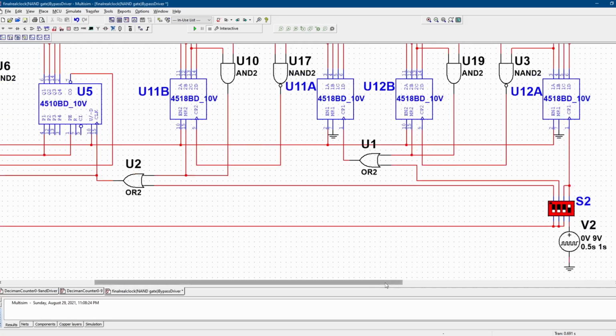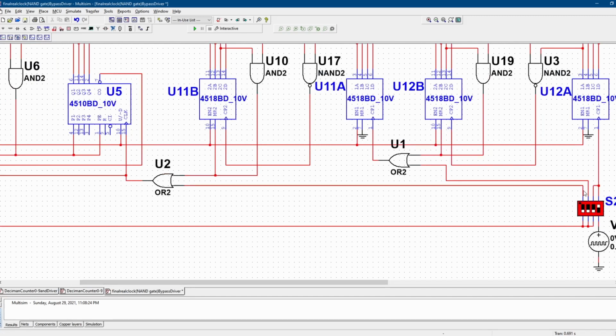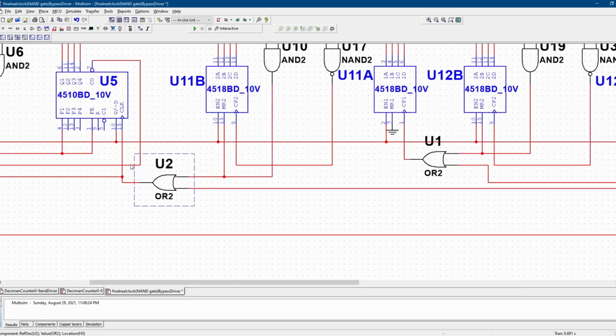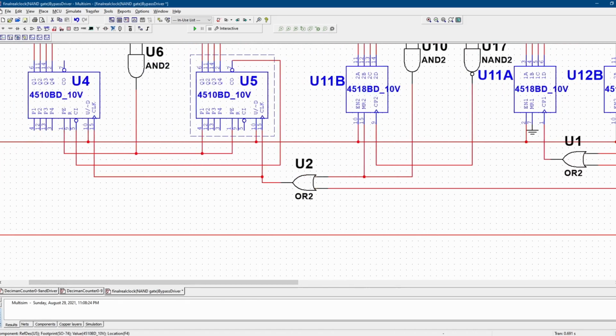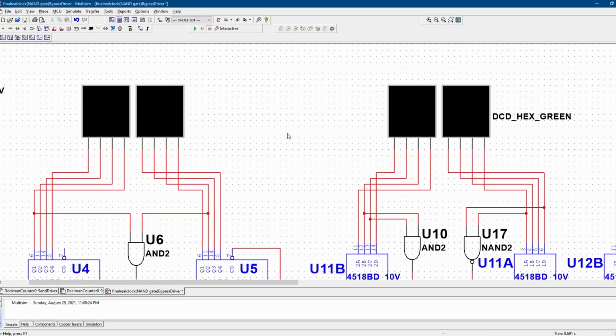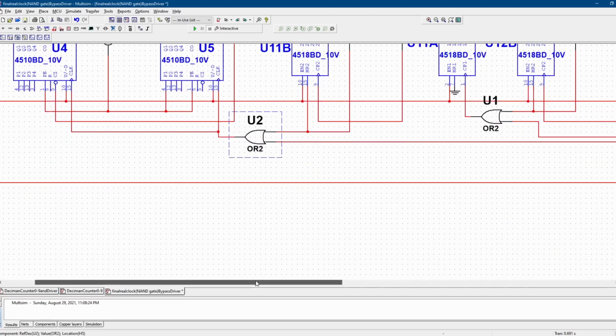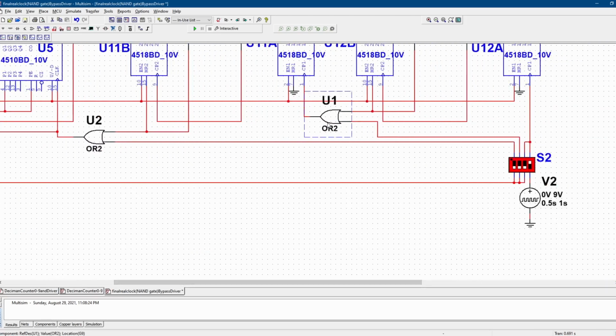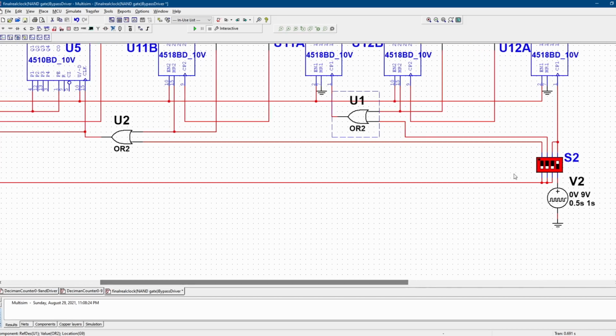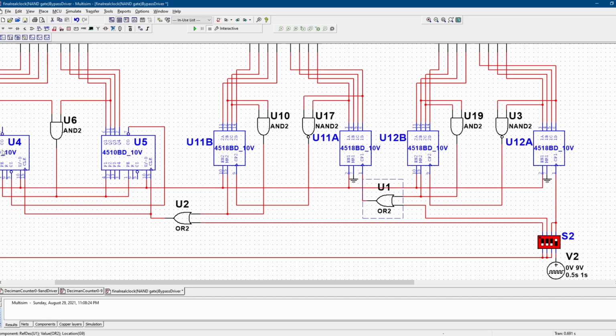And then likewise with the hours, this switch will control this logic gate here, and then if we send the 1 into here, this OR gate will activate, and it'll introduce a clock into this counter, and then I can adjust my hours. So if we look here, this logic gate is for the hours, and this logic gate is for the minutes. So okay, enough talking. Let's go ahead and run the thing.